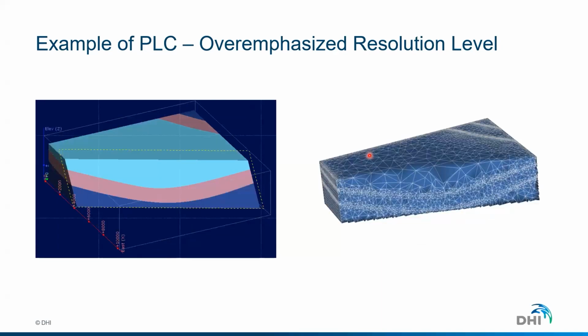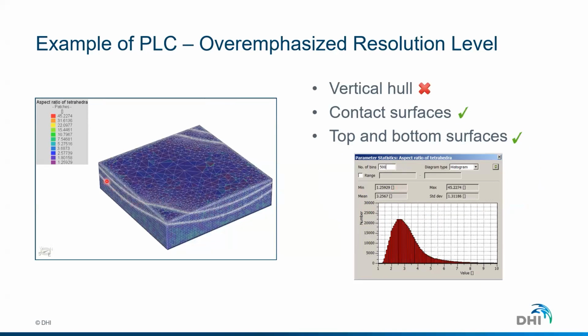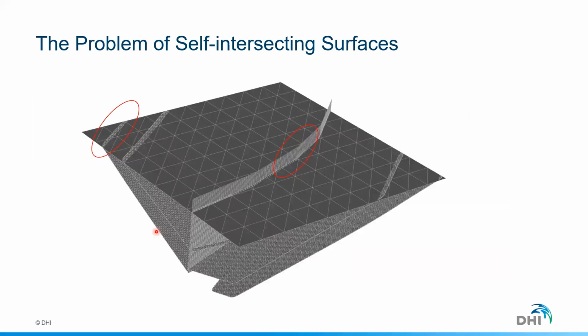That's the example. If we clip the geological model and at the same time we clip the FEFLOW model, FEFLOW preserves the geological contacts very well, but in this case is probably emphasizing the discretization around the vertical faces a lot, because the input data comes in that manner. So we need to improve this, and it's not that easy to improve it directly from the geological software. That is why we take the next steps in our development roadmap.